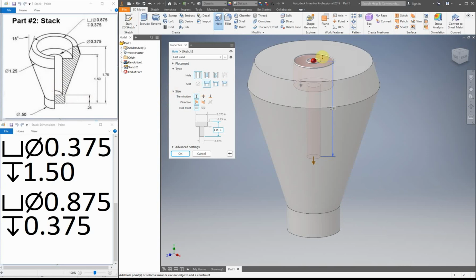So right now we just kind of set up how the shape of it's going to be, but not the size. So now I can look at my different components. So these are currently the defaults of all of this, but this is not what I want. So looking over here, it's a little hard to see what's going to go where, because these are put in the opposite order that you would expect them to be in. It's actually putting the smaller diameter hole first and the larger diameter hole second. So if I'm looking at this, I'm actually going to look at the bottom for my diameter. And to select what you want to type, you just got to click on it.